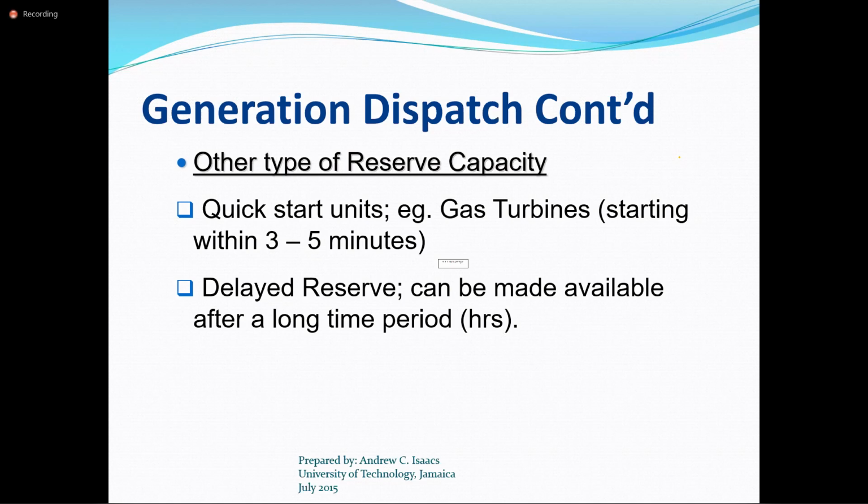And those generators, based on the protection systems that were in place, also pulled out from the system. So the entire system ended up collapsing. So the short answer to your question is that no, there will be no automatic trigger for a generator to come online. That is something that needs to be watched by persons at system control.